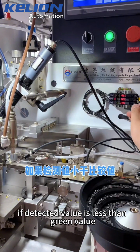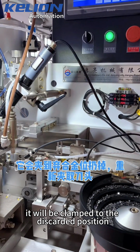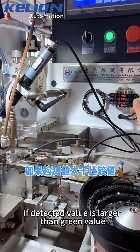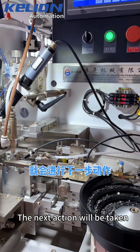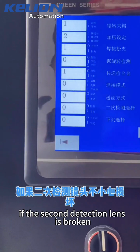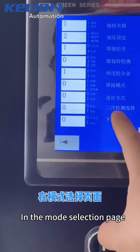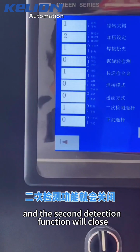During operation, if the detected value is less than the green value, it is a wrong carbide tip. It will be clamped to the discarded position. If the detected value is larger than the green value, it is the correct carbide tip. The next action will be taken if the second detection lens is broken or there is no second detection. In the mode selection page, change the second detection selection to 1 and the second detection function will close.